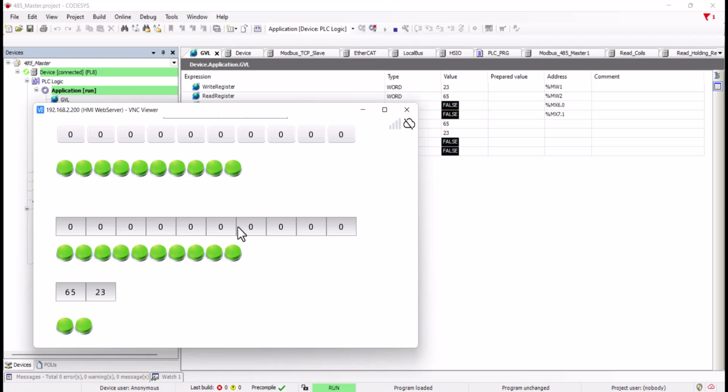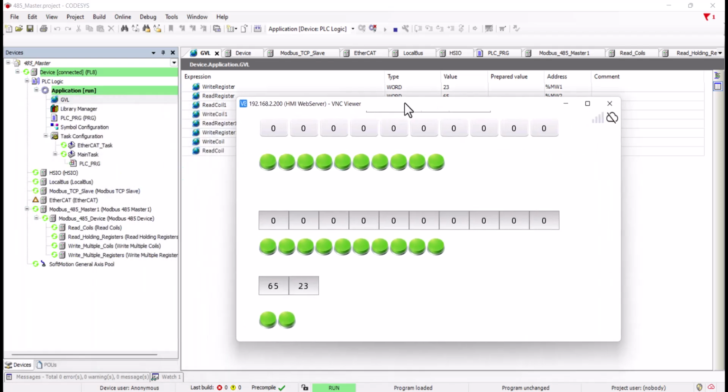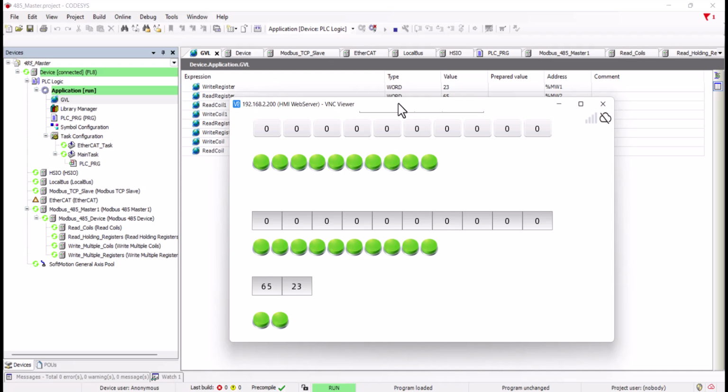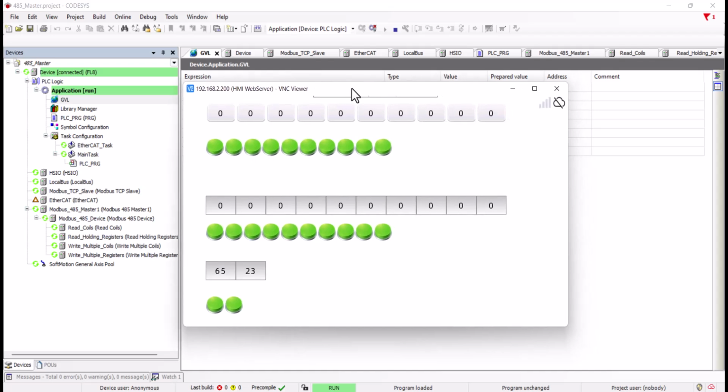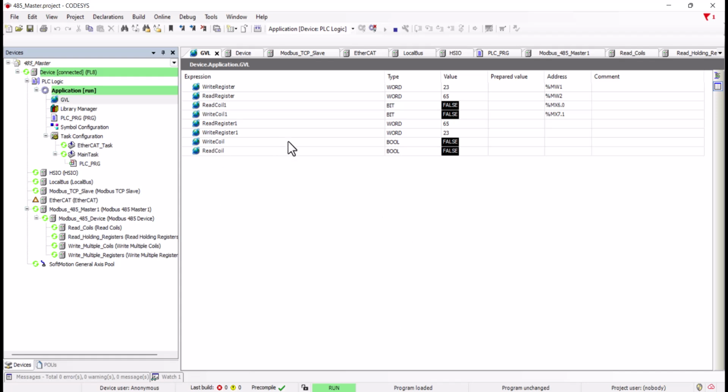So if you want to communicate between PLC and HMI by Ethernet cable, it is recommended to use tag communication. It is much easier for configuration, and the address mapping is more convenient because you just choose the variable tag node to match the variable address one by one. So that's all for the communication parts. Thanks for watching.